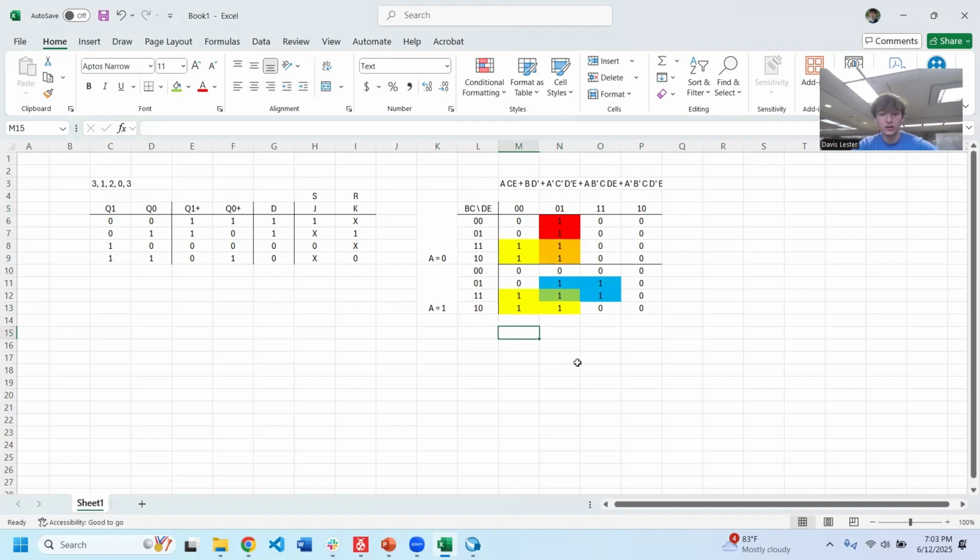So we're going to write D as being false, so not D. Then A changes, remember, because we have that 3-dimensional, so we can ignore A. Through here, C changes from 1 to 0, so we can ignore C. But we're going to keep B, so B will be true. I'm going to add a plus because we're doing OR.